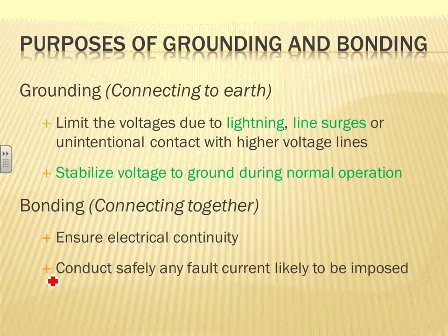Talk about an assembly line. You get that power through the assembly line. The first ground fault, the first hit, you're still standing. You get another ground fault on a different phase, now you're down. Who cares, if you're a manager counting dollars, you're guaranteed one chance, and then you can monitor if you have a ground fault. You can say, great, now I can have any ground fault in my facility and my facility is still making whatever it's making. So it's good for reliability.